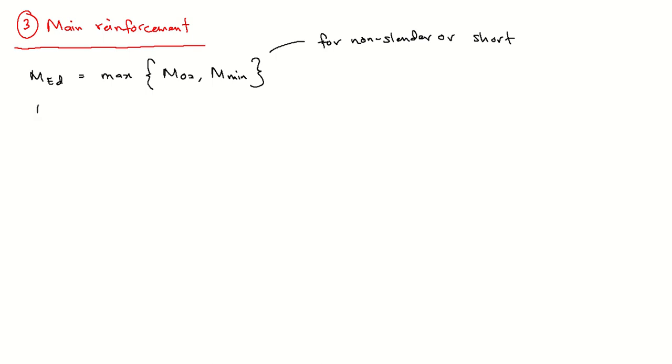Let's figure out M02. M02 is equal to M top, the higher value, plus the M imperfection. We have calculated this: 18.39 plus 3.55 is 21.94 kilonewton meter per meter. It is moment, so kilonewton meter per meter.